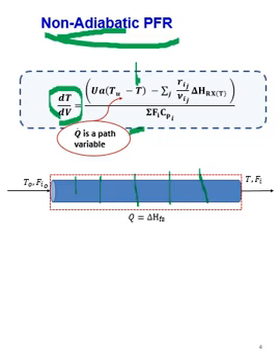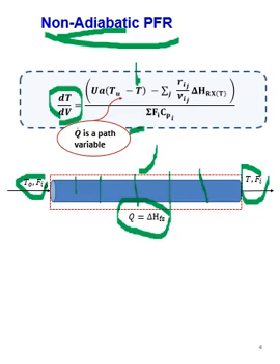It is still possible, however, to calculate the total amount of heat transferred in kilowatts, like Aspen would do it, by considering flow times enthalpy in and flow times enthalpy out, and I can get an answer for Q, the total amount of heat flowing from that reactor as a kilowatt or megawatt value.